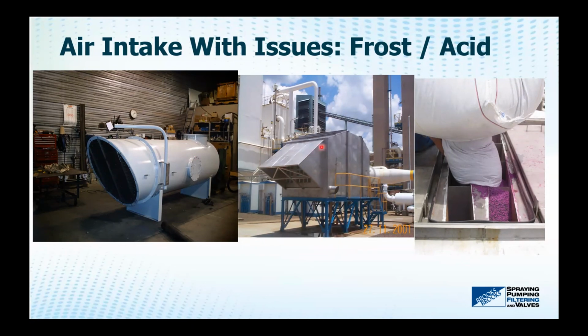The other part is that there could be chemical contaminants or acid contaminants that are present in the ambient air. And to prevent that, we use a scrubber to prevent chemicals going downstream. The benefit of that is these acidic chemicals would corrode the metal, the compressors.